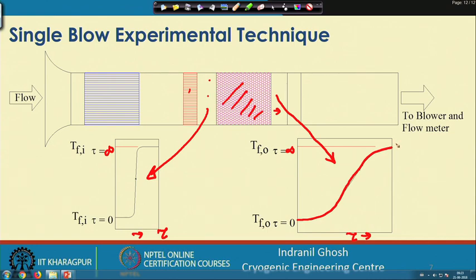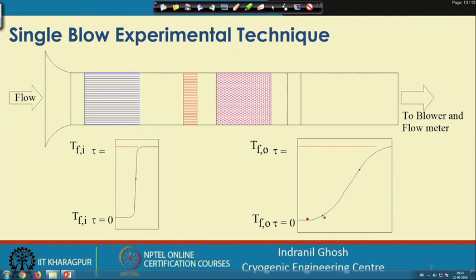Now, as we have understood from the earlier theory, we are able to predict the exit temperature depending on the inlet temperature. So, what we will try now is that we have this data for the exit temperature. We have measured these exit temperatures, and theoretically, as you have noted, this theoretical prediction of the temperature profile will have a parameter called h. Now, we will put different values of h to find out which value gives a good prediction of the heat transfer coefficient or the temperature profile.